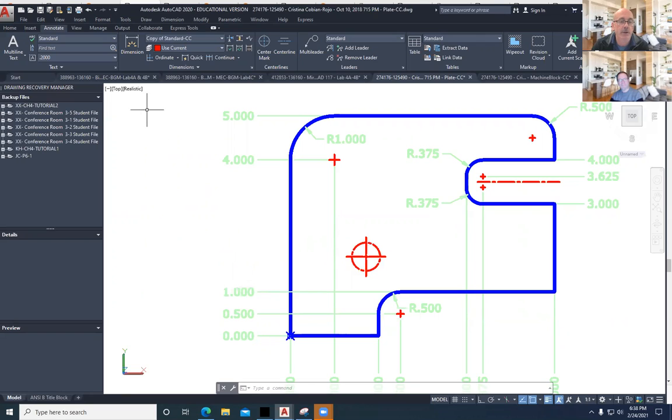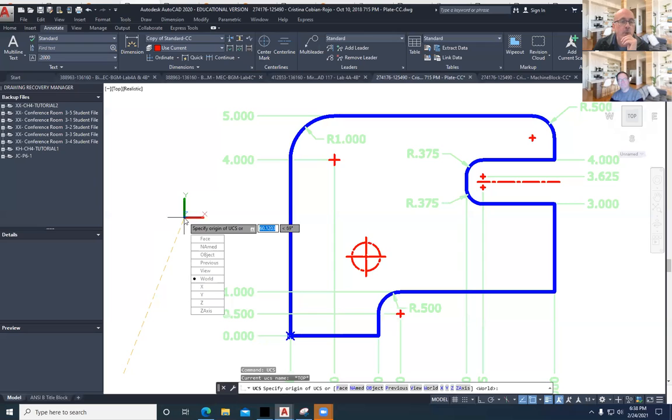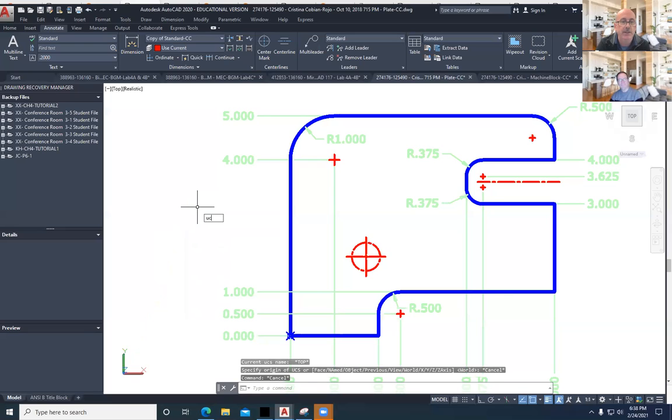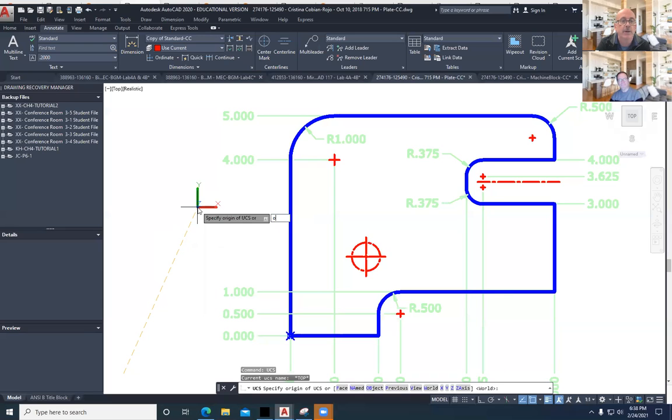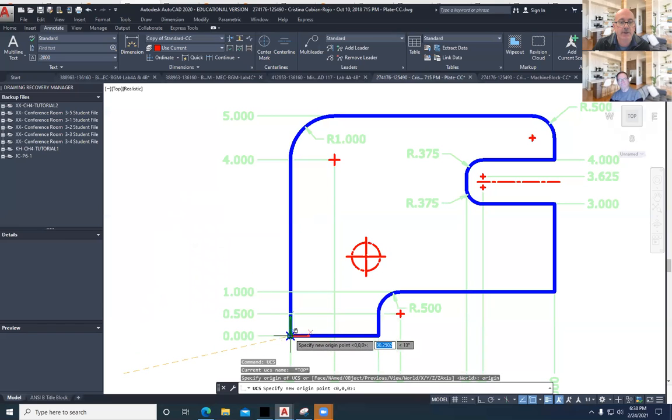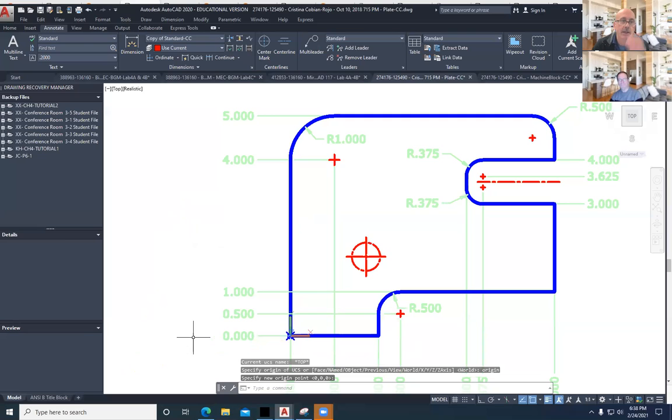And so if I were to go here, I think it's my UCS. And so I'll say UCS, and then I'm going to go down arrow, and I'm going to put my origin. I'm going to have to just say O for origin because I can't find it. UCS, origin, and I'll put the UCS origin right here. Bam. Now I should be able to get an ordinal dimension.